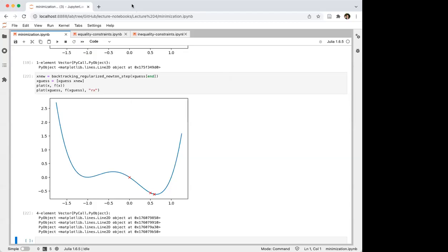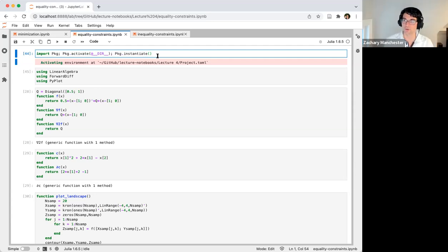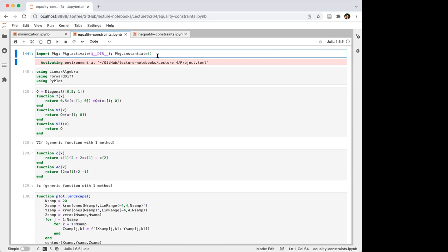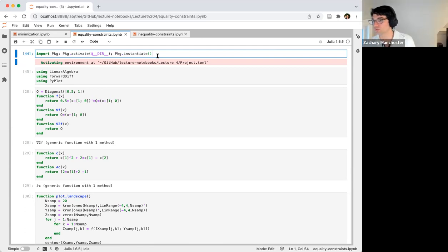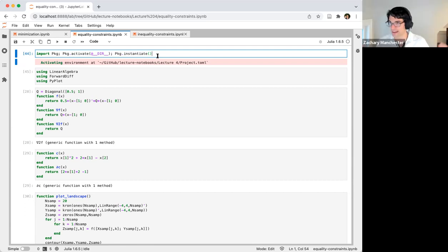I have a question about that simplification. Does it depend on the constraint, if it's actually simple versus more expensive? Yeah, for sure. There are definitely situations where that term could be super cheap and you don't care and it's fine. But often in optimal control in particular, these constraints are the dynamics of our robot. If you're talking about a humanoid robot and this being the manipulator dynamics of some really complicated robot, computing the second derivative of your dynamics is often really expensive. So in that context in particular, it's usually not worth it.